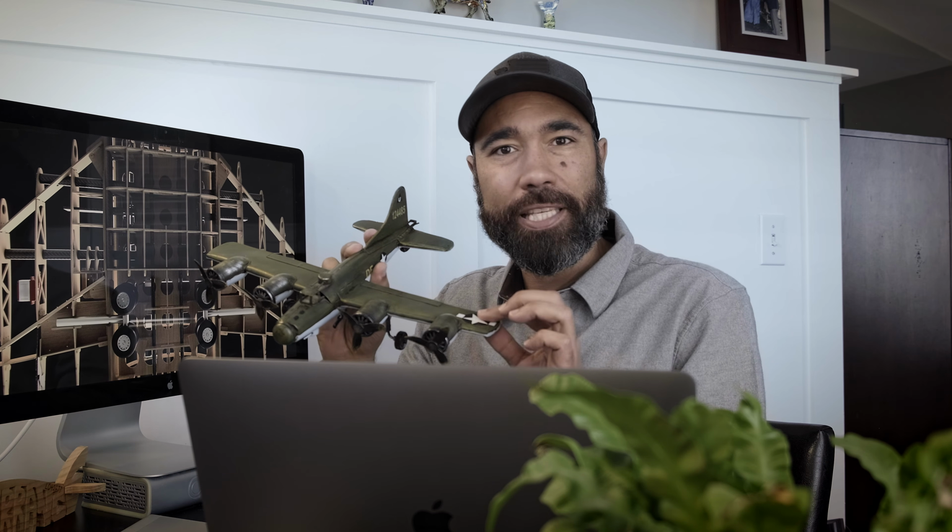If you don't add that into your wing, you'll end up into what they call a wingtip stall, which really isn't a thing, but where you stall and now you don't have any control because you've lost the smooth airflow over the tips where your ailerons are. So for that reason, it is a very good idea for you to add washout in your wing design. So enough of the little tiny washout lesson. Let's get back to Fusion 360 and wrap up this episode.